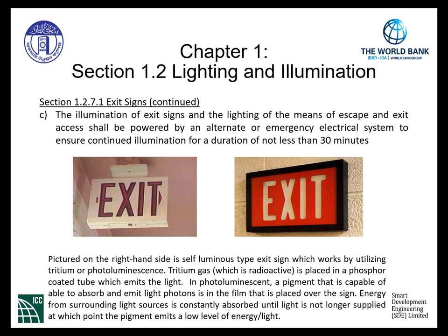The picture on the left-hand side is a powered, illuminated exit light that needs building power. On this type of light that requires building power, there is an accessory that can be purchased that has a battery backup in these exit light fixtures. Most of these come with 30-minute, 60-minute, or 90-minute duration.